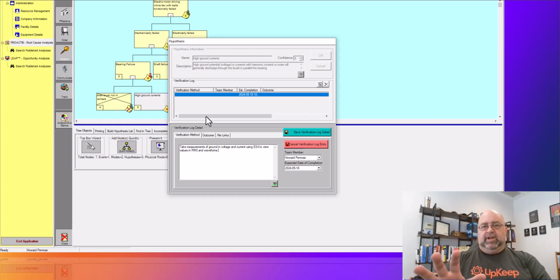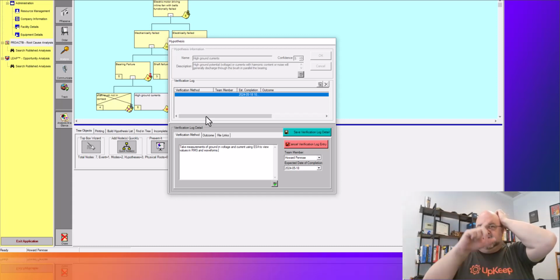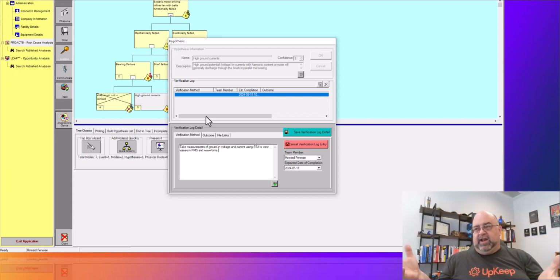Okay, this is really important that you see what the waveform looks like. If it's a nice sinusoidal thing, it's probably not going to be causing problems. But if it's very jittery and I have a lot of harmonic content in it, well, here's what happens. I hit different frequencies, and some of those frequencies do things I don't expect, like not go through the ground brush and instead go through